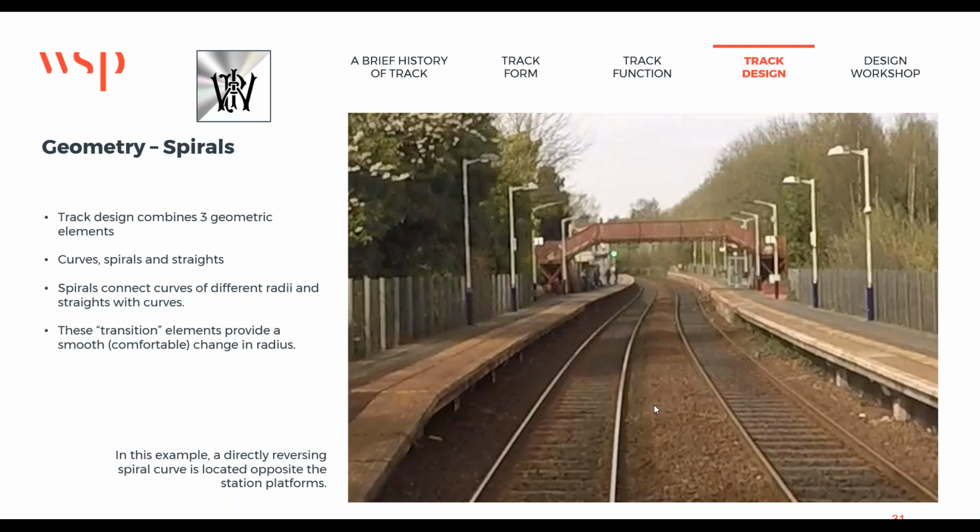Tom, do you think lateral resistance plates in the forefoot in the area of the cross walls would help? I'm not sure that it's a lateral problem. I think that the stiffness is more related to the top going off, the cant going off, twist fault starting to occur. Well, it's effectively sort of like ballast migrating, if you like.